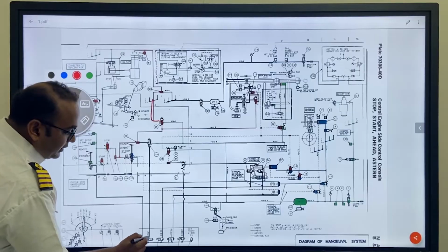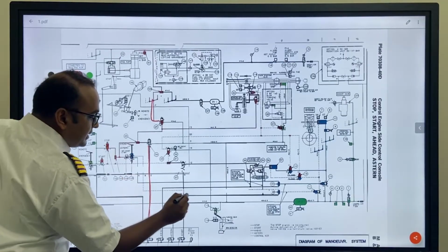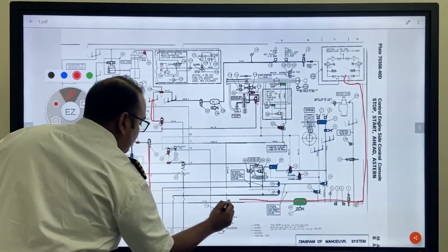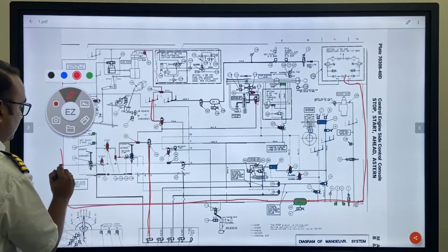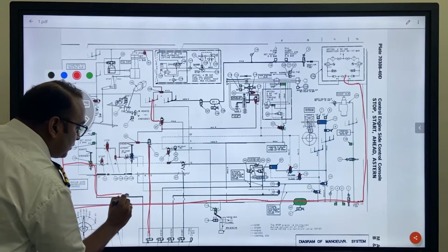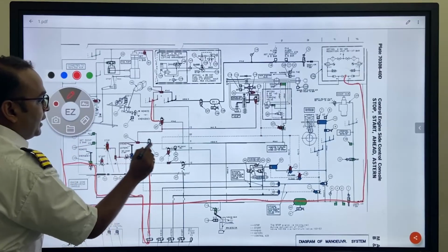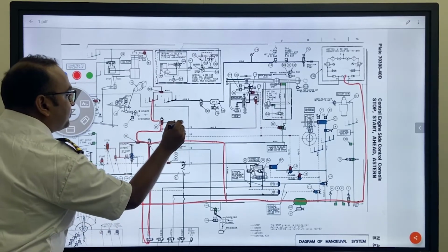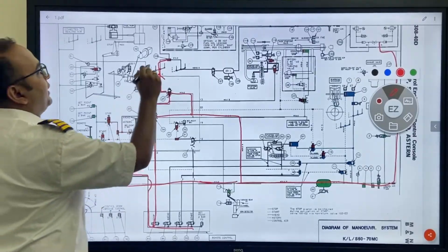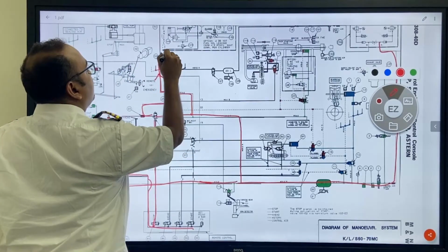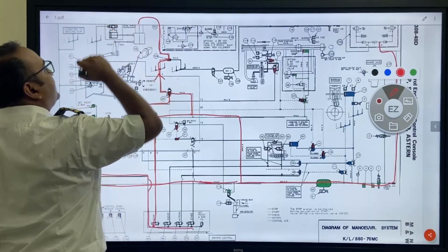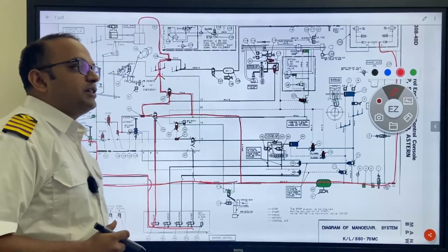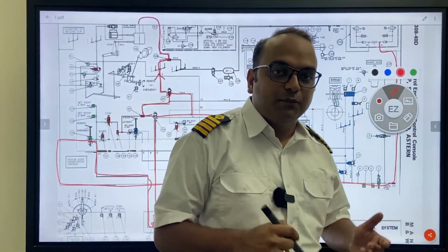So what your stop air which came like this, again I will draw. Okay, this air went up like this. So we have come to a point through the double non-return valve. It went over and has activated the puncture valve, and your engine is in a locked stopped condition, so your engine will not fire anymore.